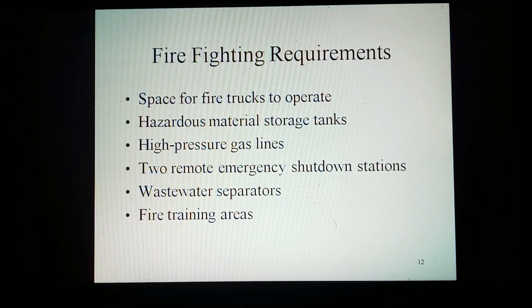Fire training areas are ignition sources when in use. Because of the smoke produced, they can also create a nuisance for the refinery and neighboring facilities. Fire training areas shall be 60 meters from process unit battery limits, main control rooms, fired steam generators, fire pumps, coolant towers, and all types of storage tanks. They shall also be 75 meters from property boundaries, administration, shops, and similar buildings and from the main substation.